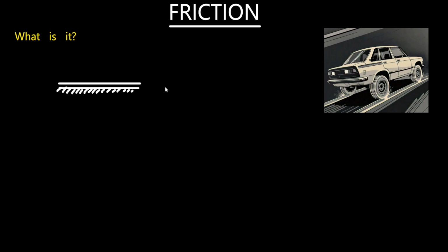Why? See, any surface you take, whether it's smooth or rough, there is always, at the microscopic level, up and down. That means surface irregularities are there in any surface. There is no surface which is 100% smooth, there is always roughness. Why do we say a surface can be rough or smooth? Because it cannot be 100% smooth, but for human eyes, relatively some surfaces look smooth and others rough. It depends upon the amount of irregularities. So a smooth surface is also rough.